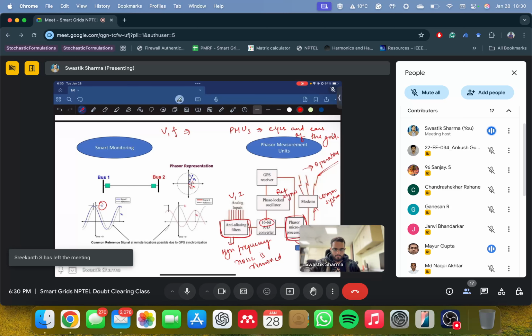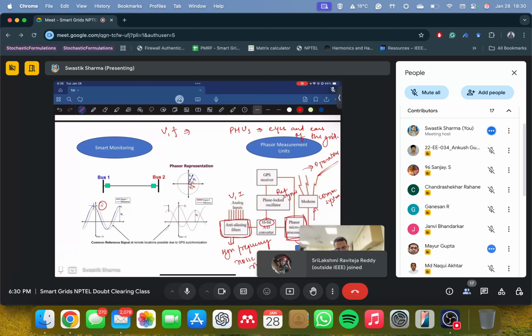The parameters we normally monitor are frequency and voltage, and those are all protected up and down, like over and under frequency tripping and load shedding, and equipment is protected by over and under voltage trips.